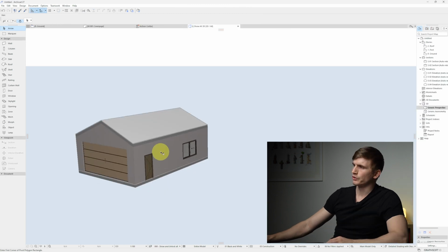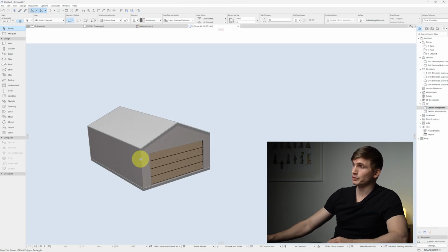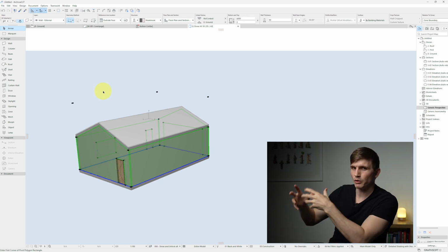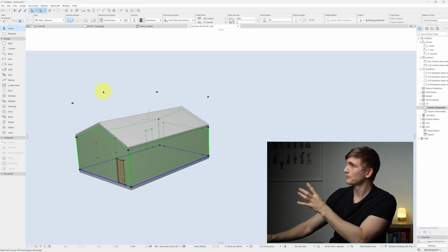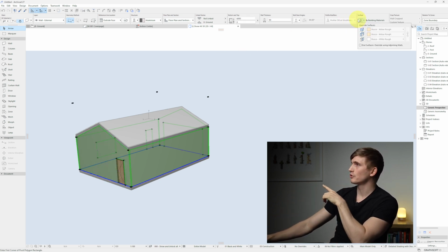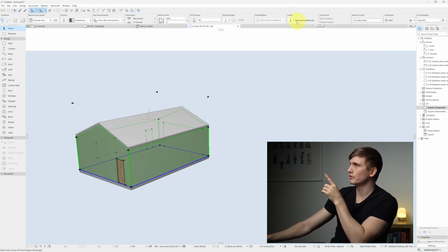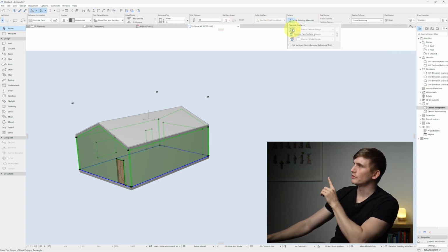So if I start off by selecting all 4 of my walls, I can do this in floor plan or in my 3D view. And that one. From here, I want to change the external surface. So I can go to surface just over here on our top panel. Now, if you can't see it, just scroll within here until you can find the surface. Now, I want you to click this left-hand side just here until it allows you to override that surface. From here, it'll allow us to actually change this surface.